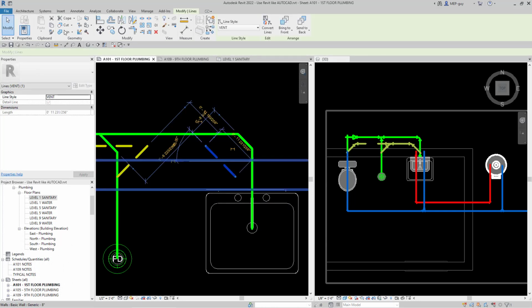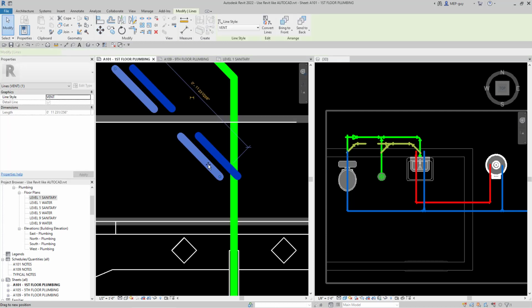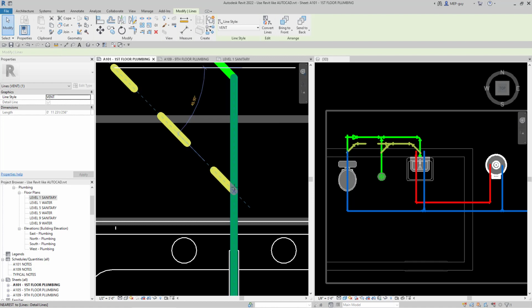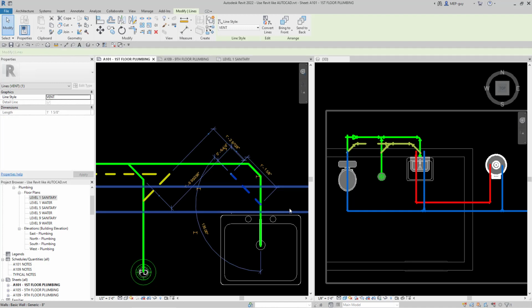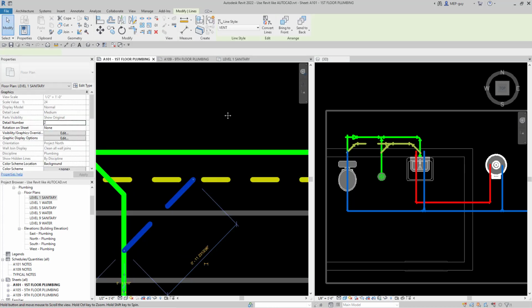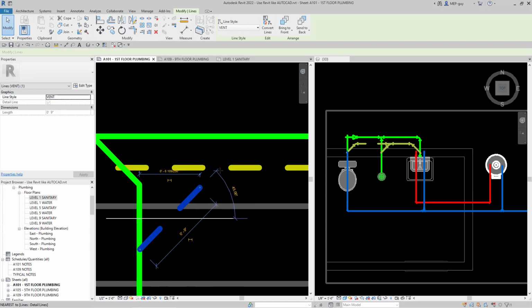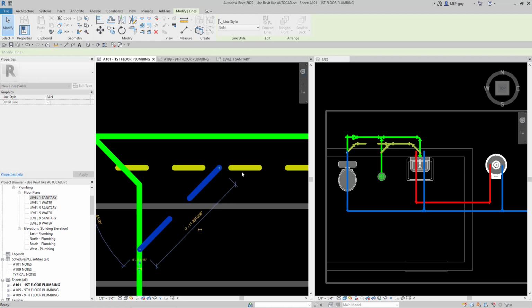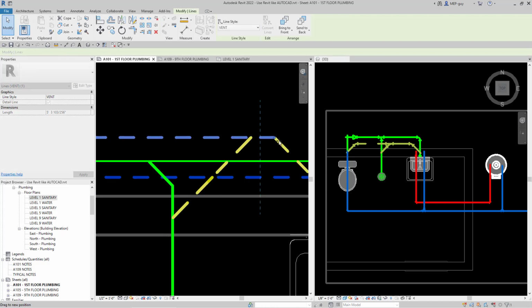We'll go ahead and just use the move command, and we'll move it to here. I don't think that moved correctly, so I'm going to actually just move it with my mouse. So we'll select the piece right there, make sure it snaps, and we can use our arrow keys again to kind of get it to line up perfectly. Use our trim command there to there, and then I'm going to make sure, like I said guys, you actually have to make sure that the lines get connected so they're a little smarter. So right here, that actually shows that it's connecting. And now when I move this vent line and I move it down, you can see everything gets connected.